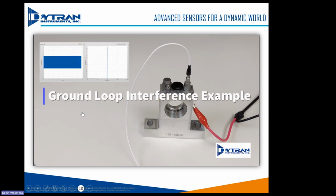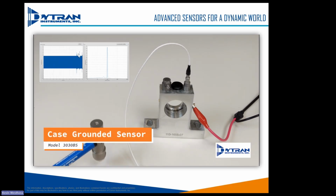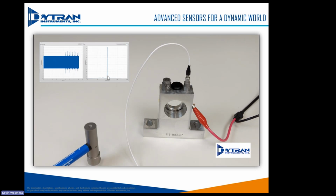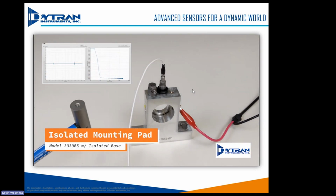So we come in, we hit the table, and look at this noise right here. This is all noise. You can barely even see the hammer. Here's the frequency content, the FFT, and it's all 60 hertz noise. So let's move the sensor to the isolated base.